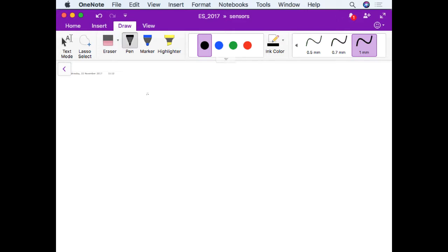Okay, so I want to finish with other common words which have a precise meaning in the context of measure. One is precision. Precision means something different than accuracy, while in common language the meaning would be very close. Precision in the context of a sensor is something related to the repeatability of the measurement.